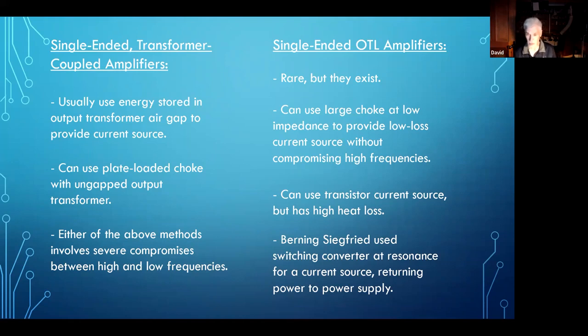It may introduce some other things that are a little less pure, like more power supply modulation, because it's more like a Class AB amplifier. But it really is, in a sense, a single-ended amplifier in that a single output tube is controlling the output waveform for the entire cycle.